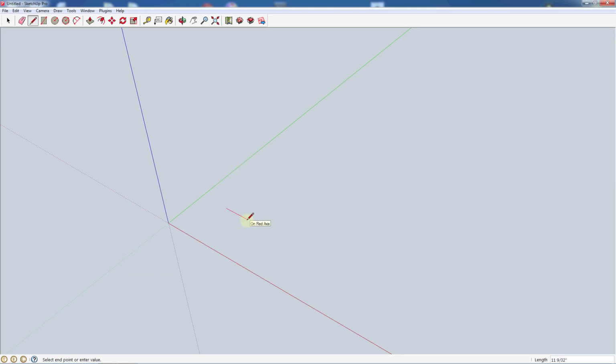But like I said, you can start your line, you can freehand draw a line. There it just ended at another endpoint. I can come up here and draw another endpoint. You'll see that it's still continuing to want to snap to different objects.